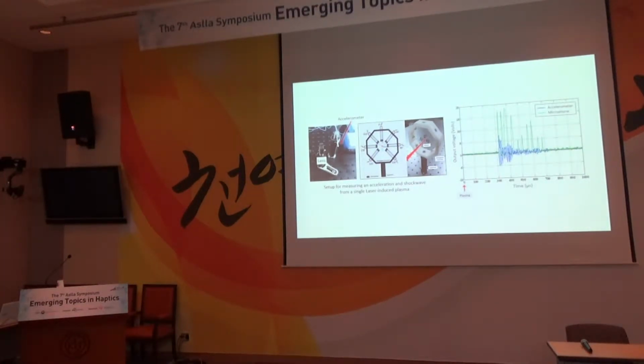We also measured the mechanical shock wave, and how much shock wave is generated. We used two measurement devices, an accelerometer and microphones here. The plasma is formed at this time, zero time, and after 300 microseconds these two sensors respond. The 300 microseconds is the traveling time through the air.